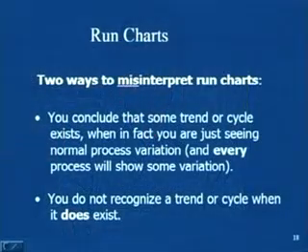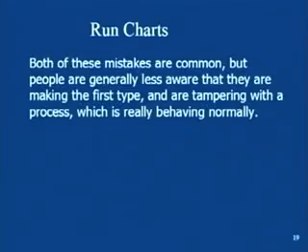So, again I am repeating, a type 1 error is when the process is in control, everything is right, but we conclude that something is wrong. A type 2 error is when things have gone wrong, but we still conclude that the process is behaving correctly.